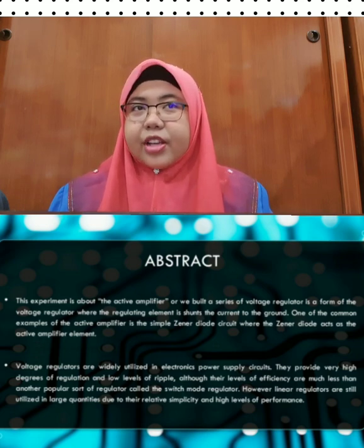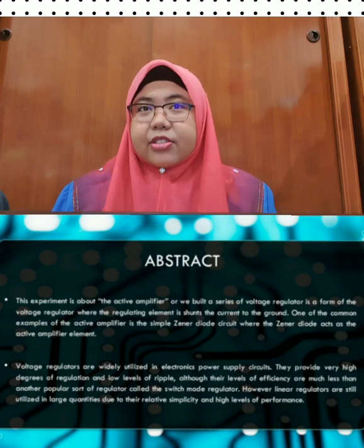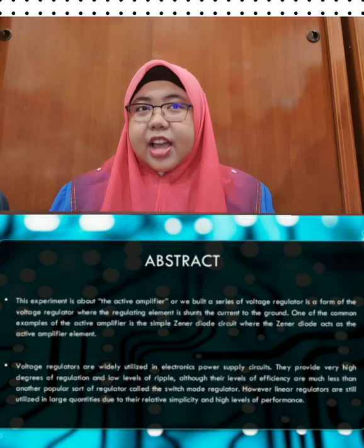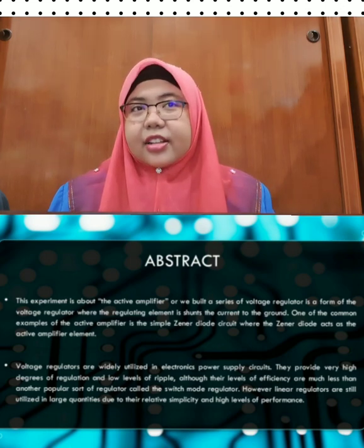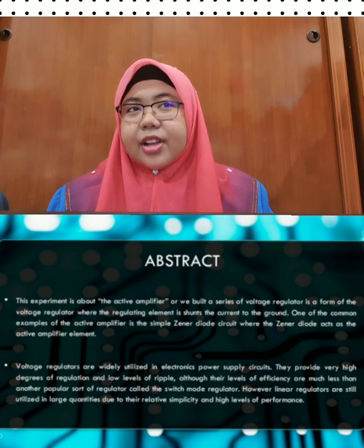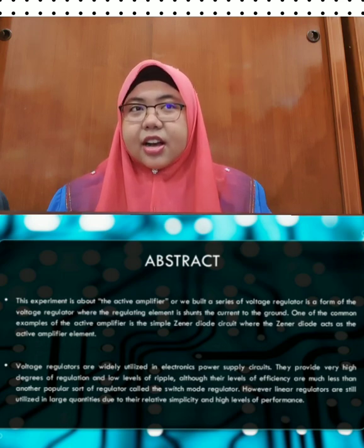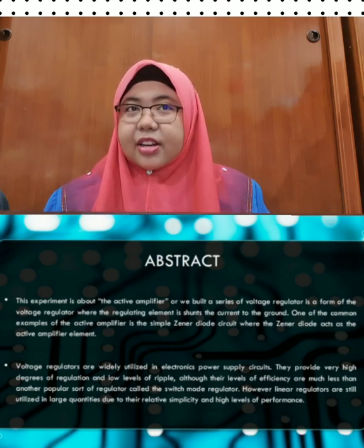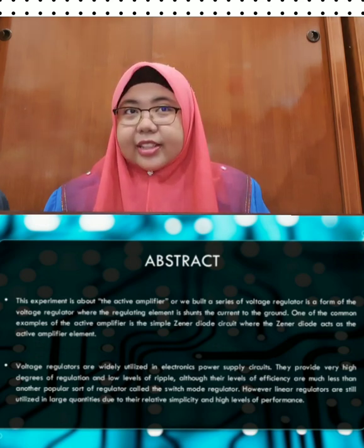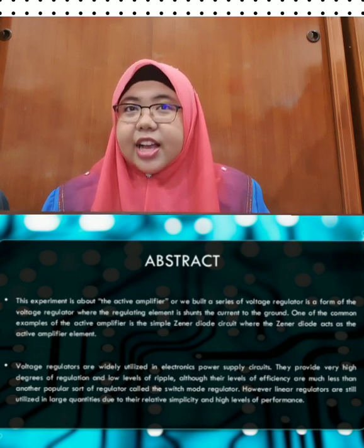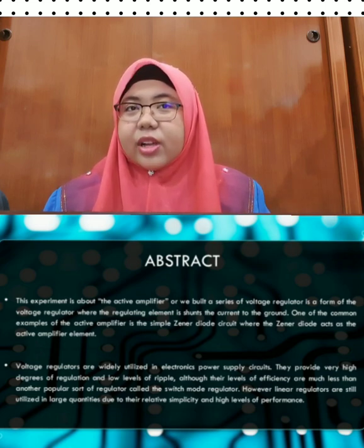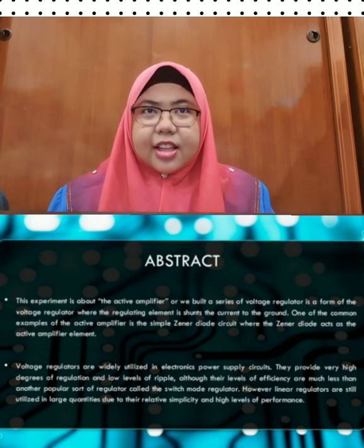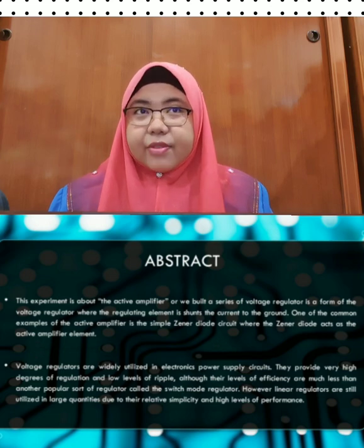They provide a very high degree of regulation and a low level of ripple, although their levels of efficiency are much less than another popular sort of regulator called the switch mode regulator. However, linear regulators are still used in large quantities due to their simplicity and high level of performance.